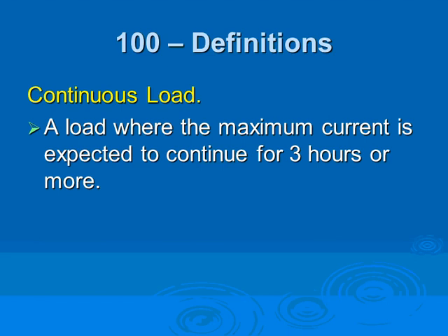Now what happens if we have a VFD on it and we're driving it lower, and we're pulling out of it, say, 25 amps out of 50 amps, because we're not driving it as much? We're not utilizing the full power of that device. Then based on the NEC code book, this is not a continuous load, right?